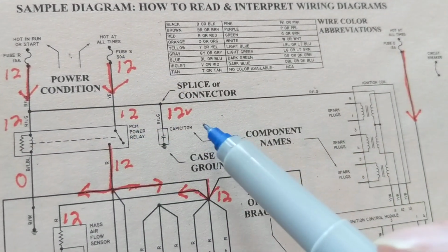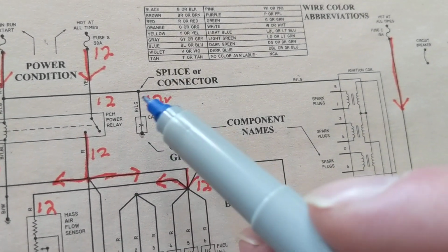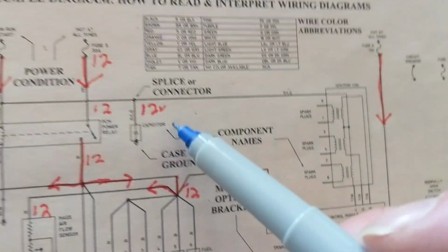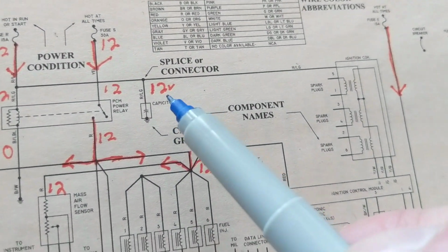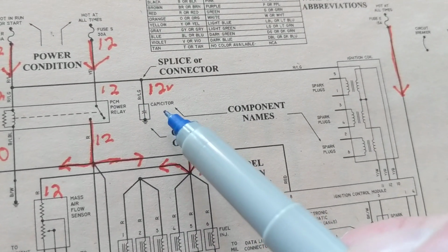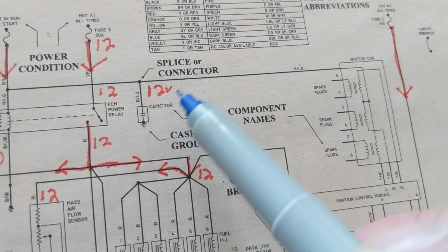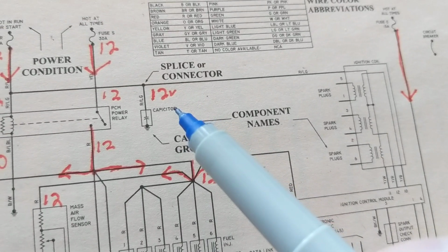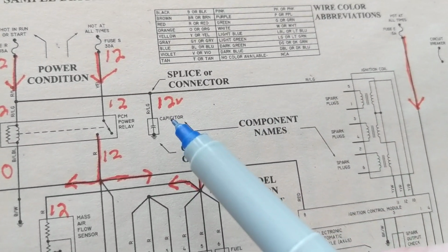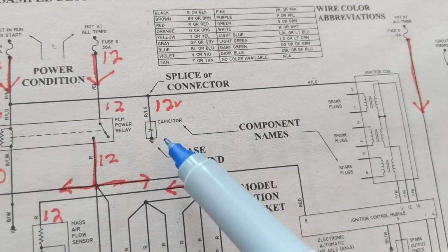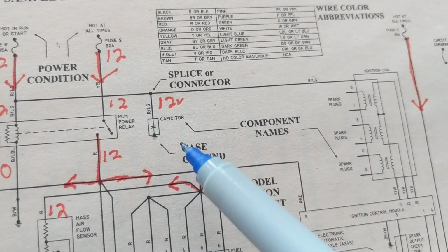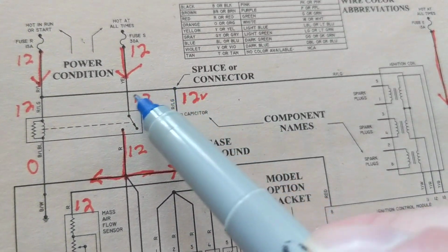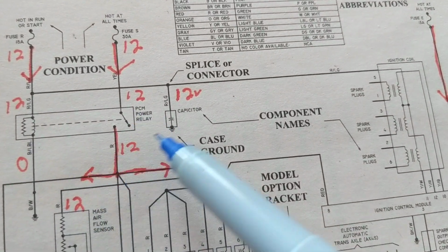While you switch off the 12 volts, the capacitor is holding a charge and it's discharging. However, if you ever see the radio is on, the clock is always on, from the battery. But the radio itself is on sometimes, and other accessories. The capacitor is providing the charge for those accessories after you turn off the switch. Now, you ever see sometimes after 15 minutes, 20 minutes, your radio goes off? Why? Because the capacitor is slowly discharging the charge it has through another component to ground. In this case, it's going through this coil to ground. So it's discharging the charge through this coil of the relay to ground.